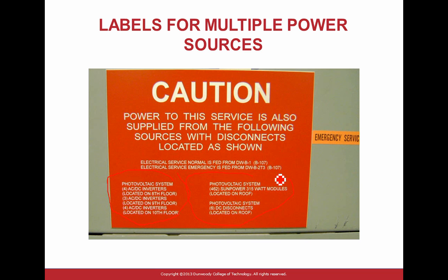Do you guys know how we wire kitchens in the US? We have something called multi-wire branch circuits. So the electricians do multi-wire branch circuits. The multi-wire branch circuit brings one circuit here and one circuit here, one circuit here and one circuit here. So we test this one, no power. He assumed that there's no power here. So anyway, he grabbed it, I'm not kidding you, like this and took it out. Got the shock of his life.